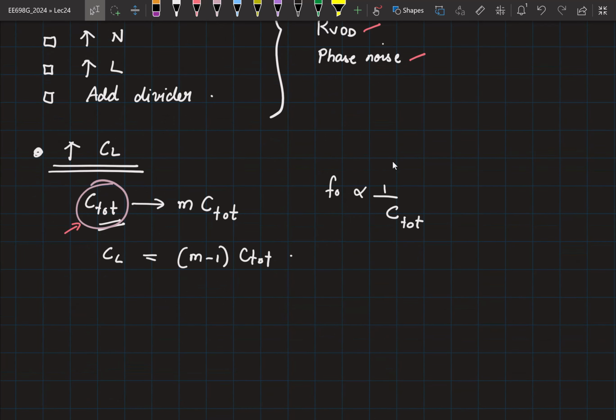You will plug in so much capacitance at each node, run the simulation, and that will tell you how close you are to the frequency. Now, based on that, you can recalculate and add more capacitance. Right? So this way you will reach the final point you require very quickly instead of running a lot of iterations. Yes. This will be in the order of gate capacitance. Yes. This will be in the order of femtofarads, provided it is not dominated by the load.